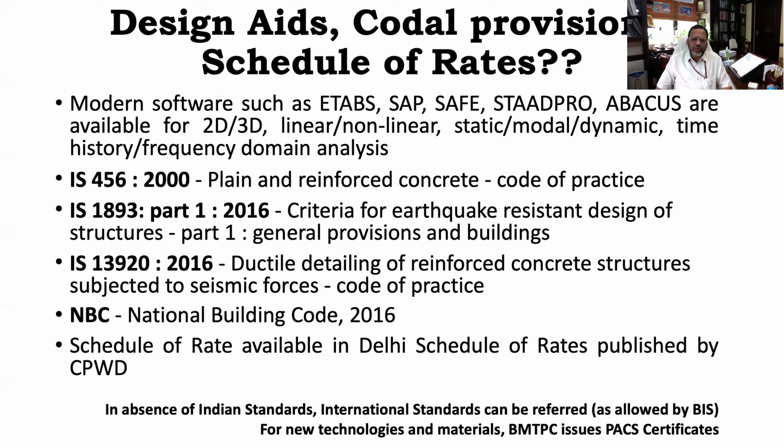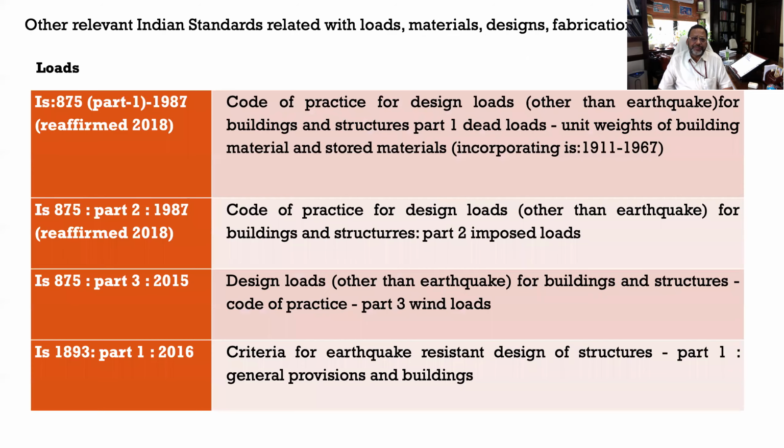The schedule of rates is already available. It has been developed by CPWD, and it is readily available in the Delhi schedule of rates. Also, let me tell you, in case of non-availability of an Indian standard, we can always refer to international standards such as British Standards, ACI, American Concrete Institute, or the exhaustive Euro codes. And for new technologies, BMTPC also issues performance appraisal certificates, and these certificates can be referred to whenever we are implementing a new technology in the field.